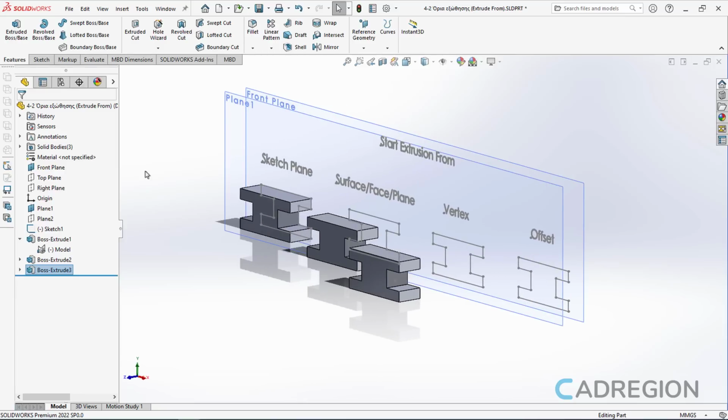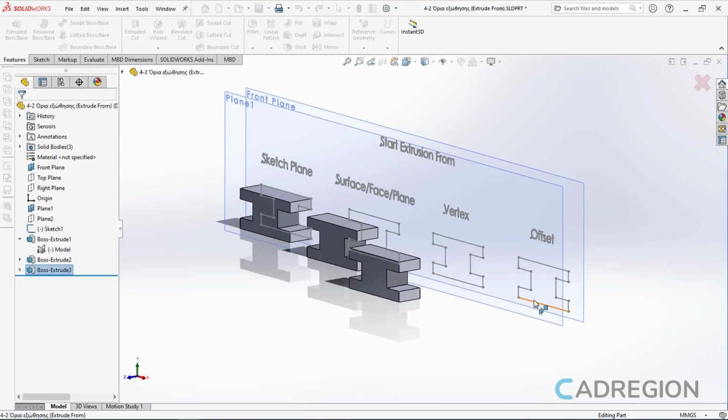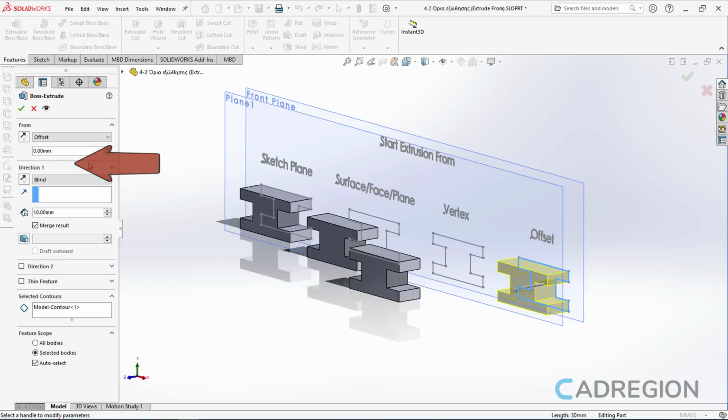Now I will activate the Extruded Boss Base tool again and I will select the last profile. I will expand the list and I will select the Offset option. Right below, the Offset field appears, and in this field I will type the number 20 and press Enter. Notice that the extrusion started 20 mm on the left of the original sketch. I will deactivate the tool and I will orbit the view again.